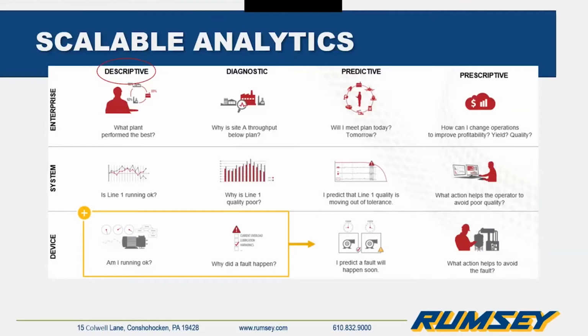And some smart devices, such as VFDs and PLCs, are prime examples of devices that already have this data available to them. And then next is diagnostic analytics. This correlates the data to determine why something happened. Like, let's say a drive faults every time there's a jam on a machine. It's correlating that drive fault to a jam.